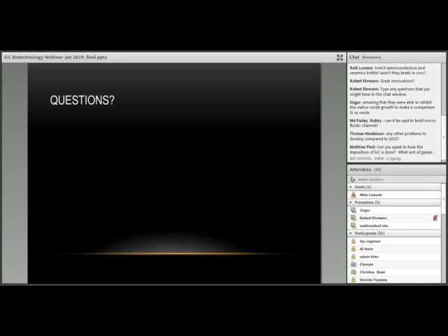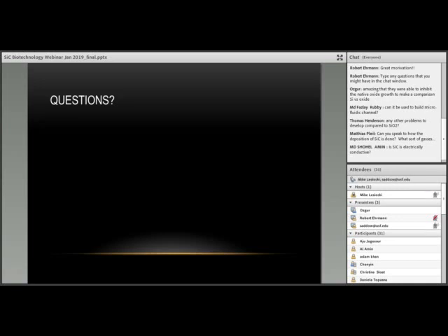That's fantastic. Yes, so we use silane as our silicon precursor. Also, we can use trichlorosilane. There are other silicon-containing gases one can use as a silicon source. This is grown in chemical vapor deposition, at relatively high temperatures. In the case of 3C, just below the melting point of silicon. And the carbon source can be your normal suspects. We typically use propane. We also use ethylene. So there's different ways to provide carbon, and of course, getting the right mass balance. We do that with mass flow controllers and everything. And anyone who wants to hear more about that, there's a very rich literature on how to grow silicon carbide. We've had this around for a long time.